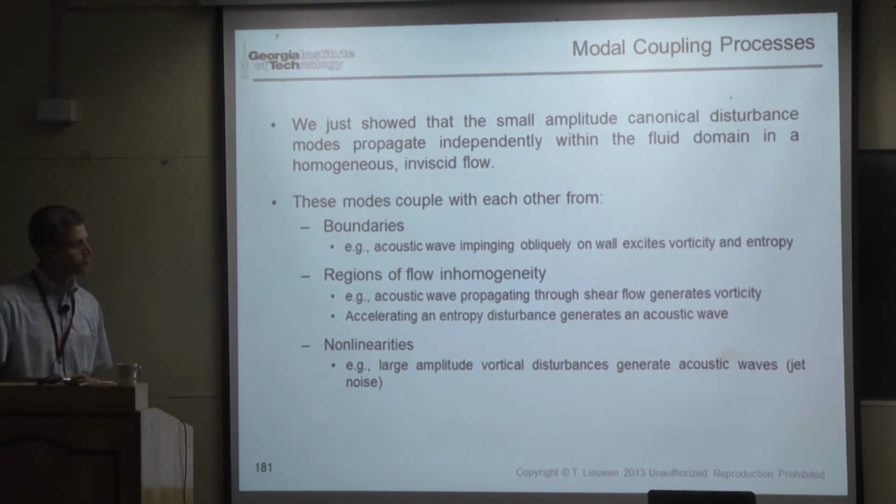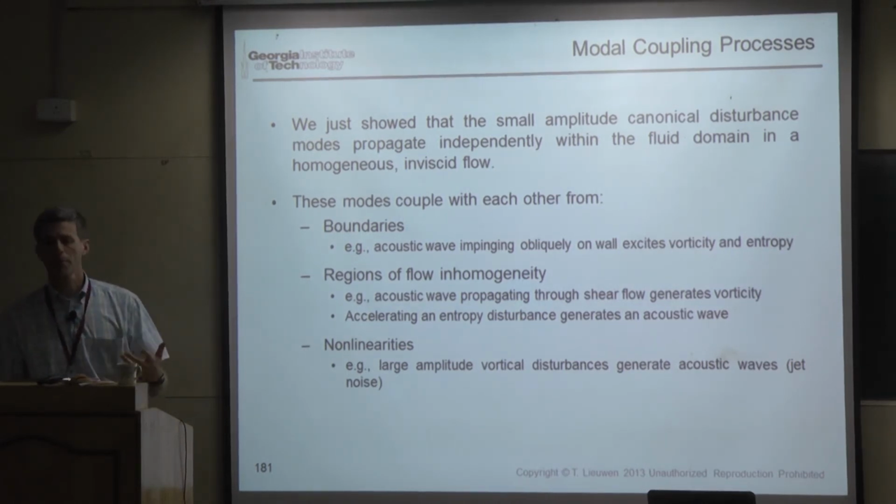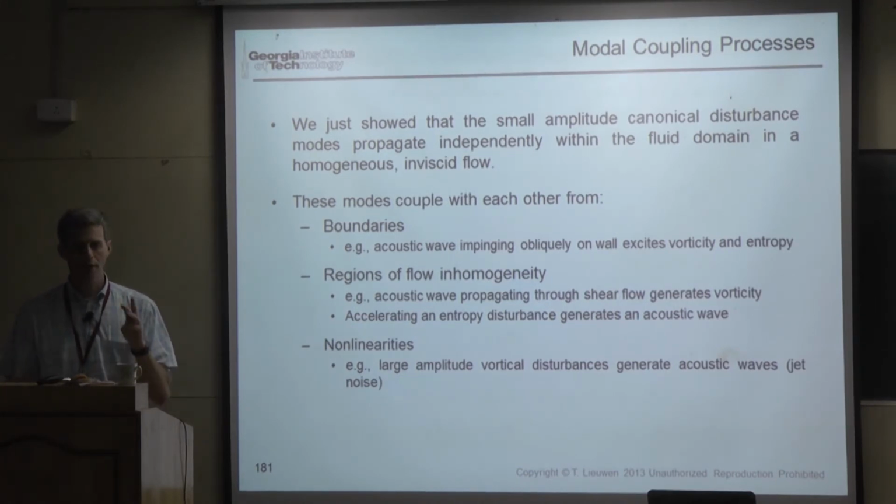And what that did was it let us see just the basic properties of the Navier-Stokes equations, and it allowed us to see that the Navier-Stokes equations support the presence of these three canonical disturbance modes, which within those approximations are independent of each other. And they're also sourceless and sinkless. There's no sources and sinks of those disturbances.